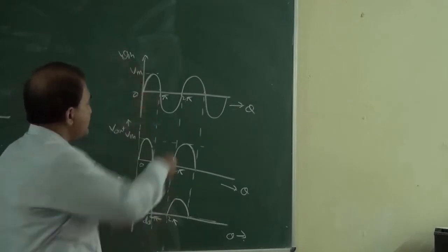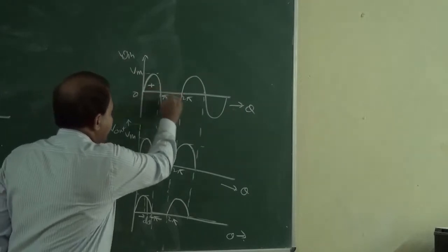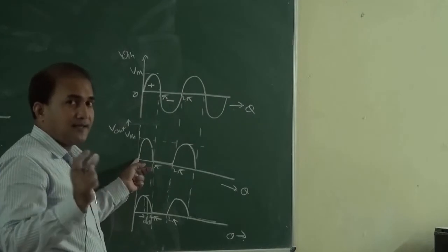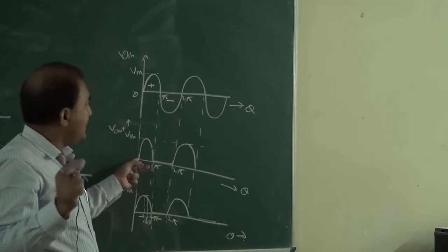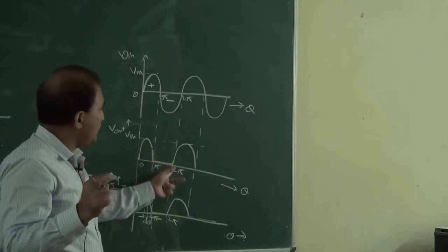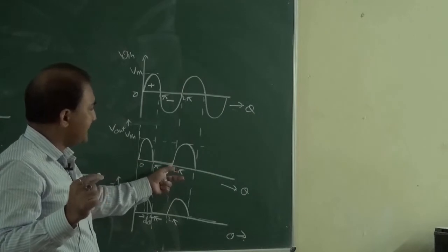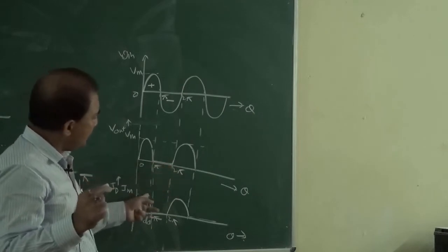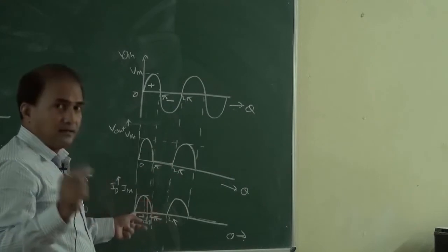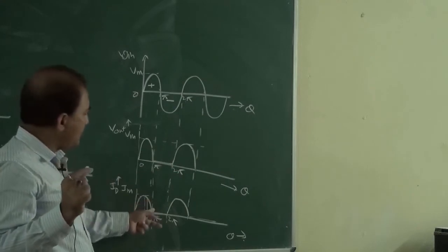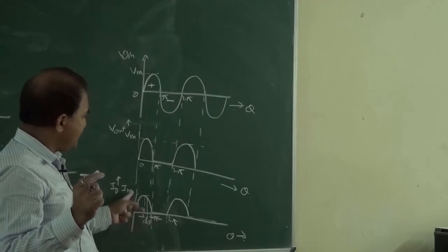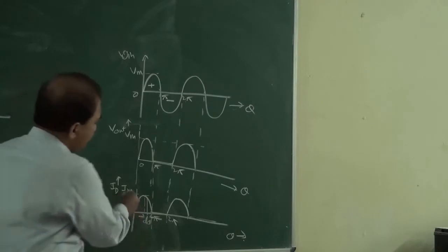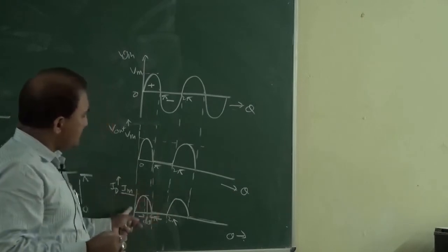So during the positive half cycle, Vout is equal to Vin if we are considering the diode as an ideal diode, and during pi to 2 pi, during the negative half cycle, V output is 0. Okay. So corresponding I naught, how we can plot I naught? Similarly, this is Im, the peak value of the current. Okay. So this is the graph.